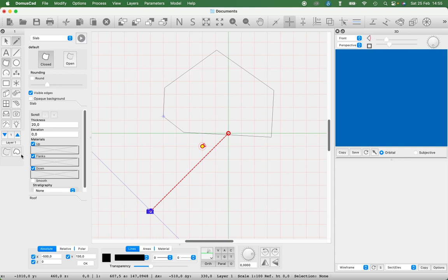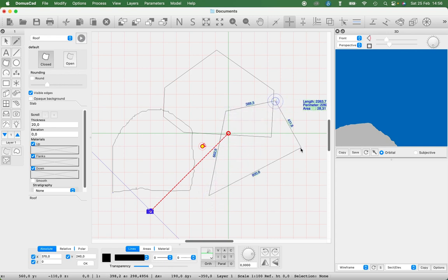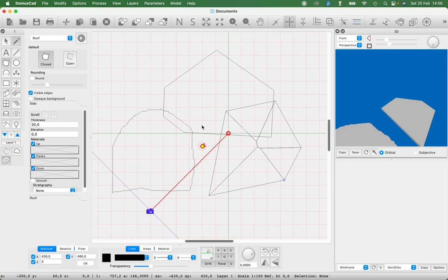The second icon below allows free input, which is done by drawing the curve in the drawing window, until the mouse button is released. In the case of roofs, there is a third input mode for constructing hip roofs. In this case, the drawn polygon represents the roof eaves line, from which the roof slopes start.